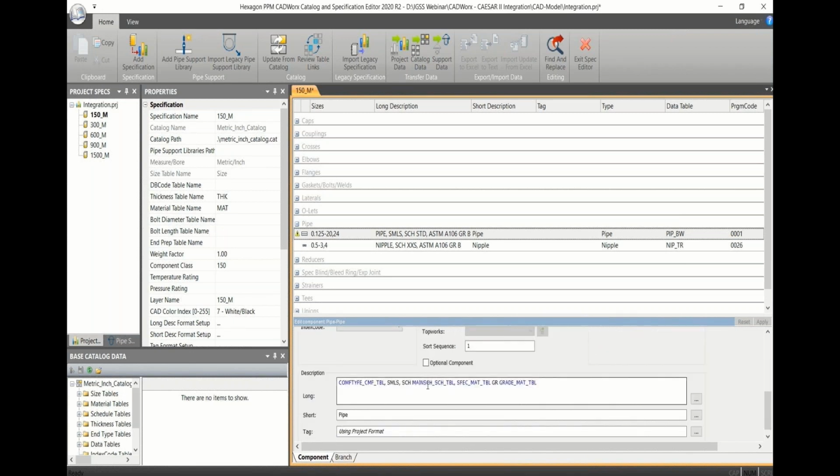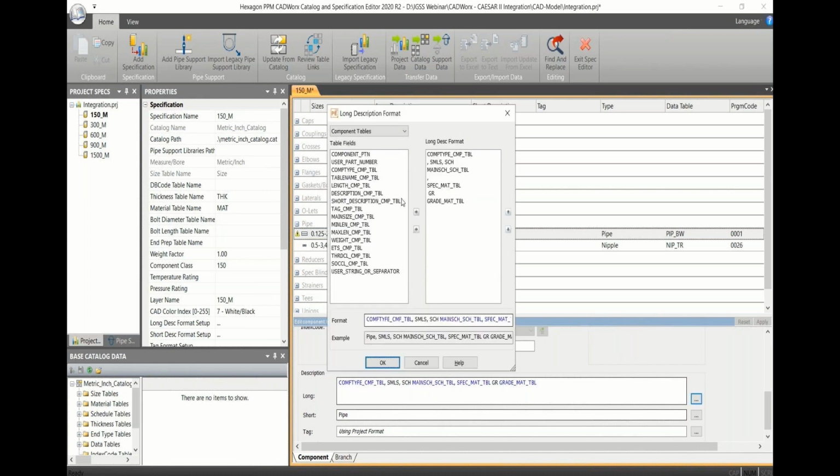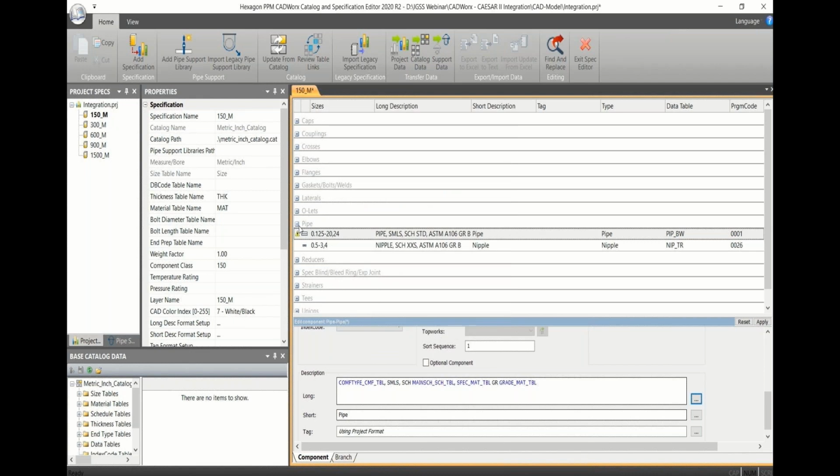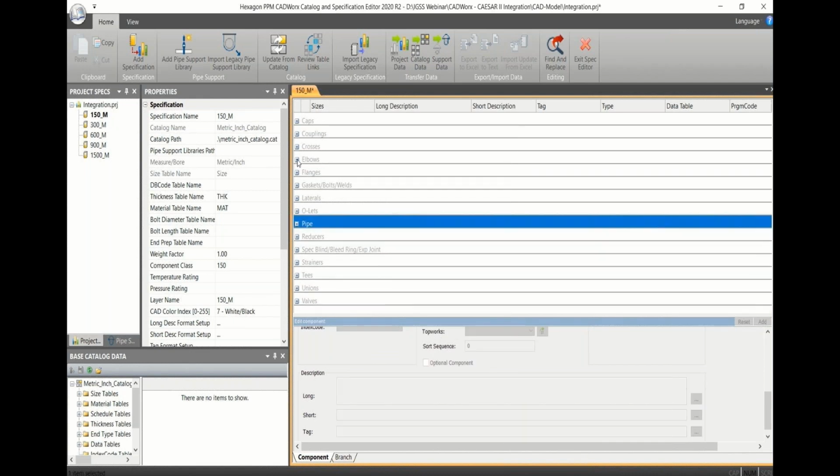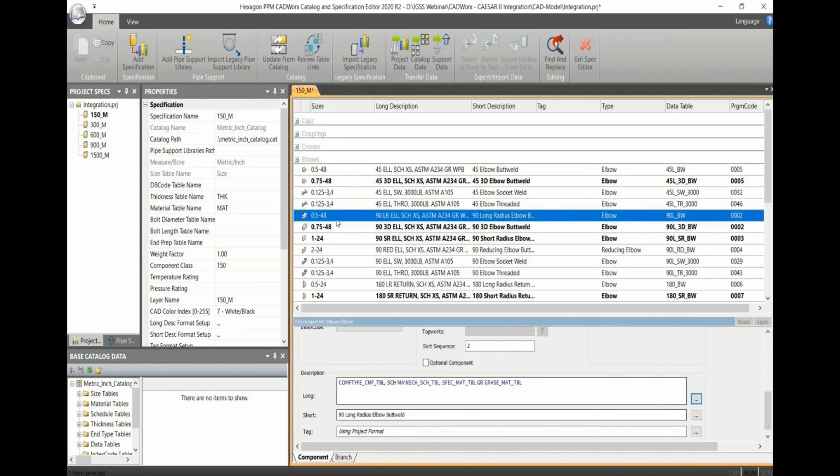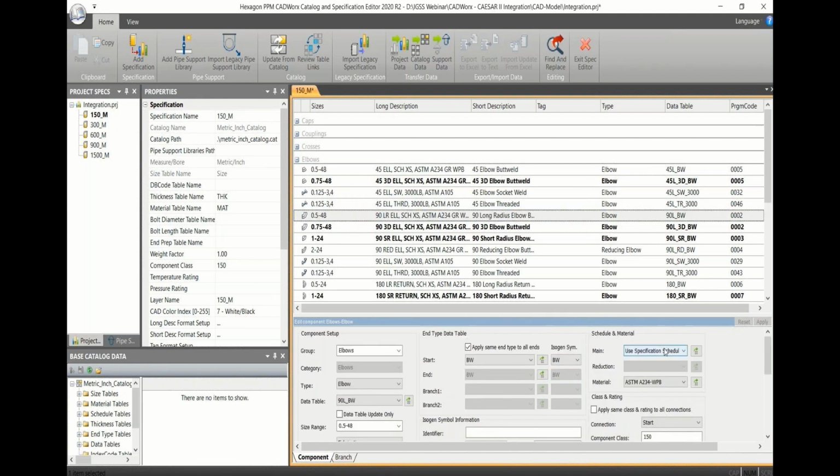And the second most important thing is the description. When we collect the details of the description from the catalog, then the schedule thickness, pipe diameter, everything will be read as per the catalog which you have defined. It's not just for your pipes, it's for the entire components. So when I give the schedule thickness as standard, I have already defined it for the standard in the catalog.